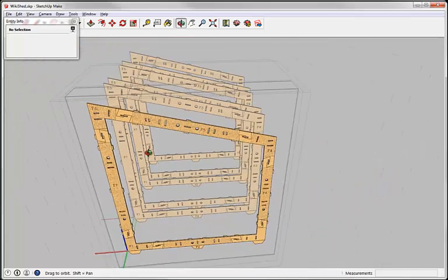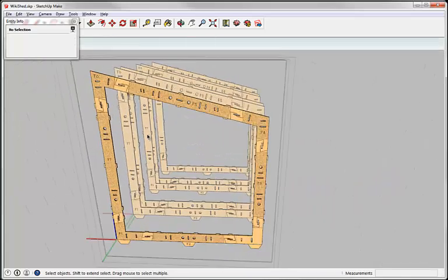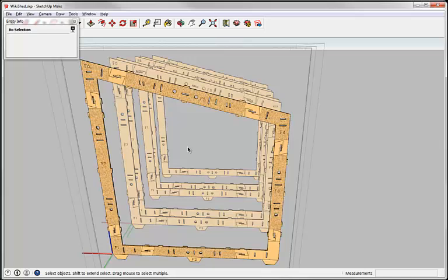The other little bit of intelligence we've added to the model is the ability to find what is the actual front face for a component where it might be ambiguous. By default, VCarve Pro will take these components, look for the largest face, assume that's the front, and lay it down flat, assuming that's upright. For the vast majority of cases that does work correctly. But we also let the user override this in cases where that might not be the right answer, or where the front and the back are of equal area, but there are features on one that mean it needs to be cut with that face upwards.